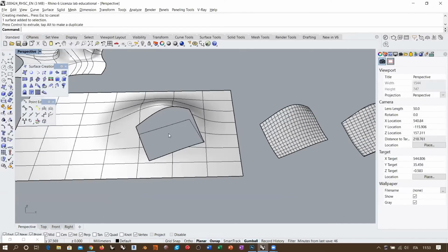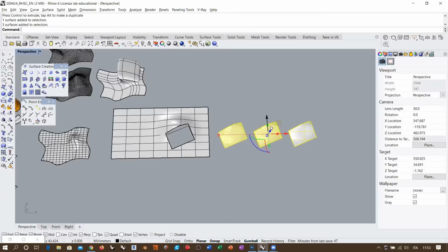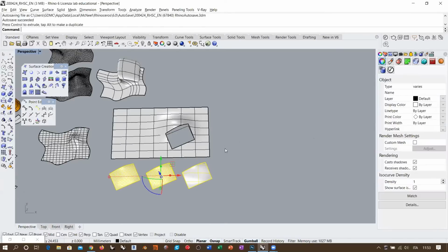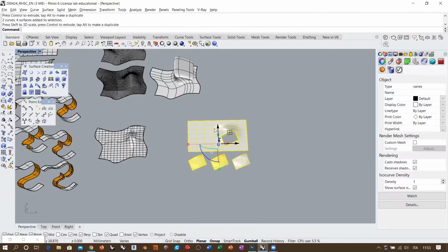Now, if you want this to be a perfectly smooth aerodynamic surface, you should also take into account that even the curvature control along the edges is producing some kind of sudden curvature variation, which is the jerk that we were discussing yesterday. In that case, from an aerodynamic point of view, this surface with this patch should not be exactly the perfect result. Okay, so you see that continuity problems become quite relevant when you work with these complex components,